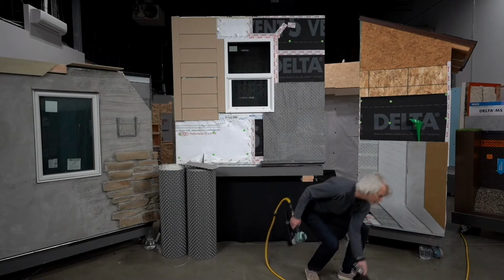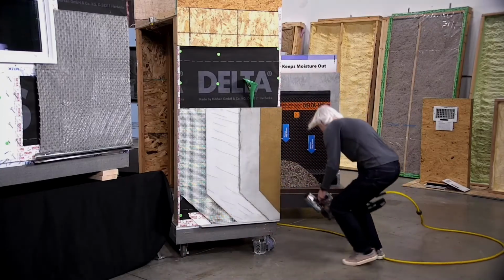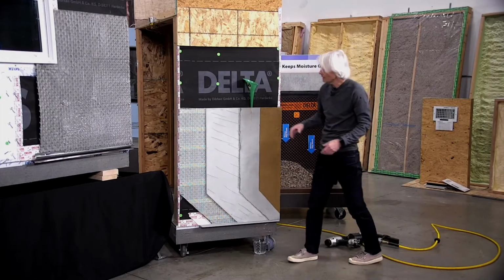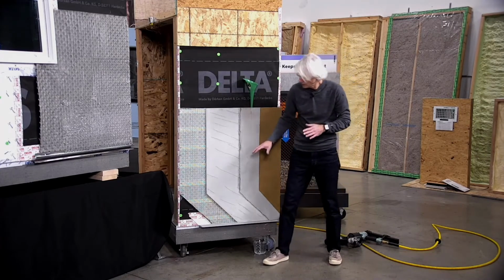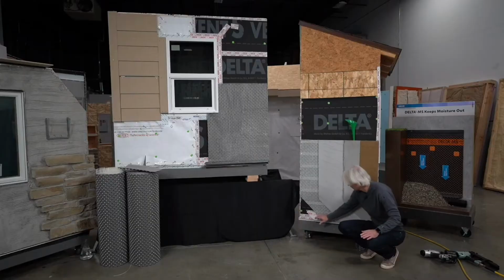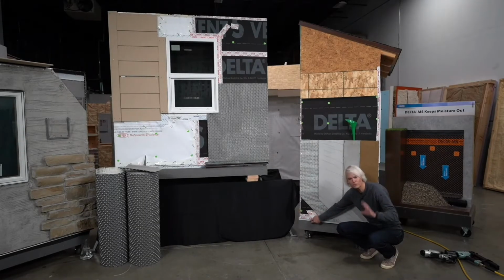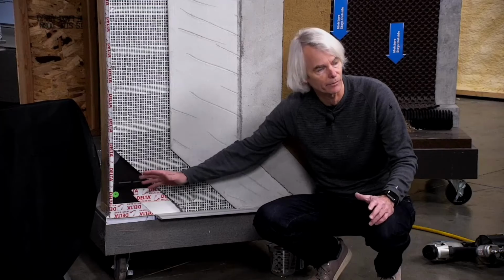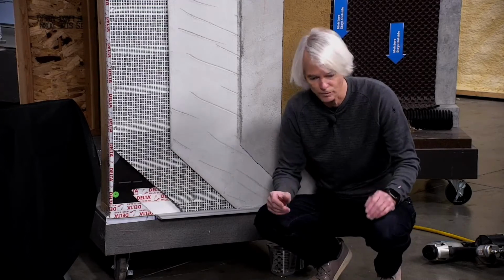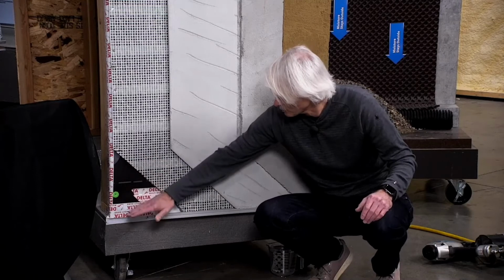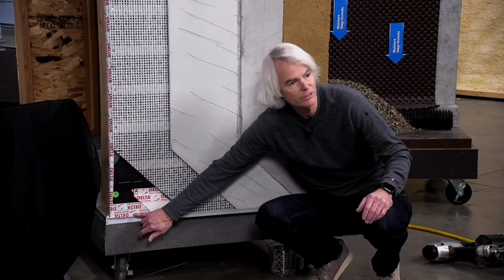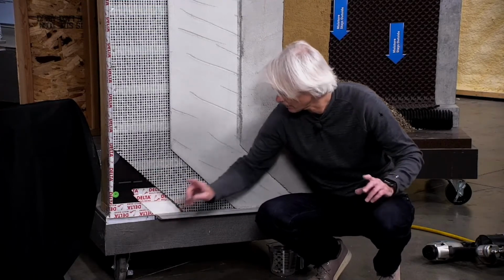Now, we're going to go over and just look at another wall that we've put together here, and we've done one to completion. And here we are to look at a few of the details at the bottom of the wall. Number one is we completed the same detail down here where we used a piece of peel and stick flashing to extend to the foundation behind onto the raw OSB or wood framed structure that lies behind it. The weather barrier layer then is lapped over the top of it, and we've seam sealed that one off to maintain our air barrier continuity.